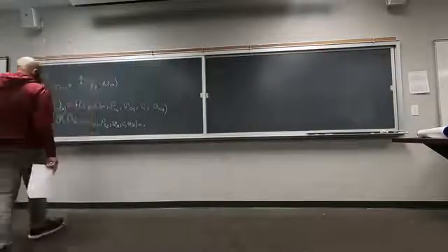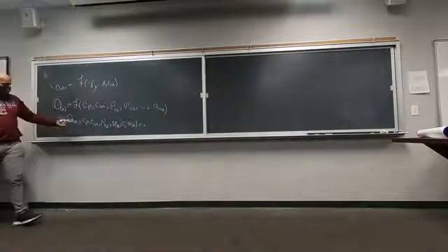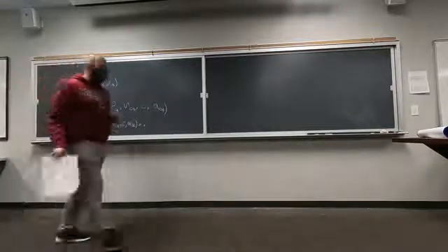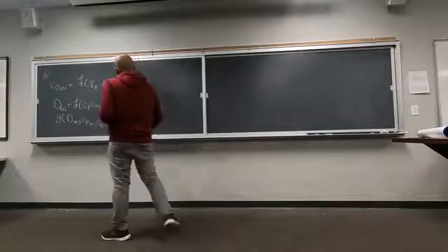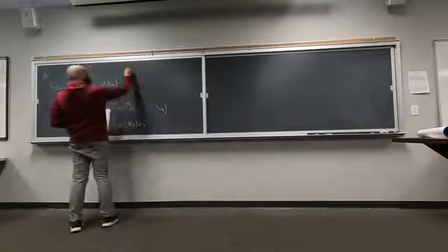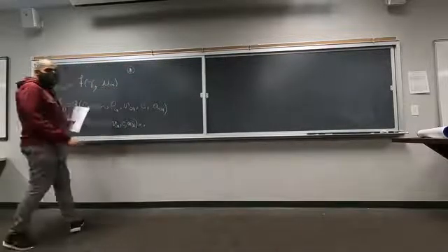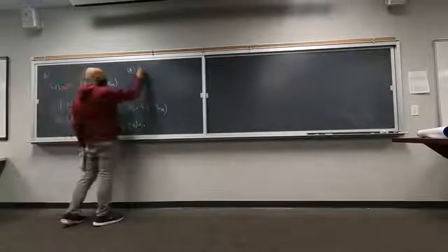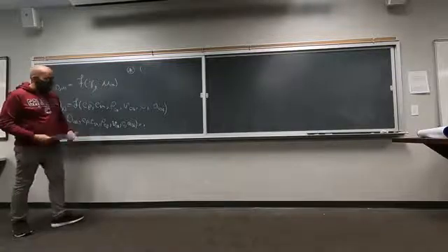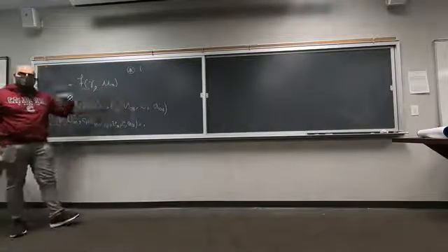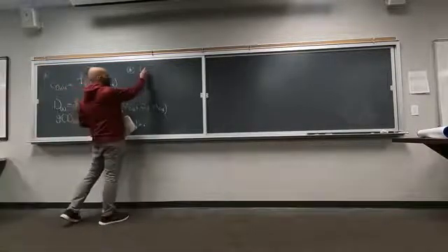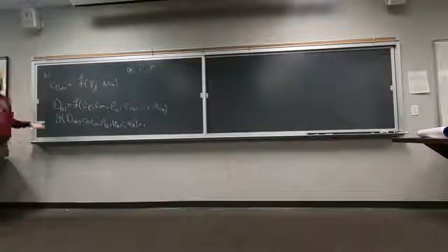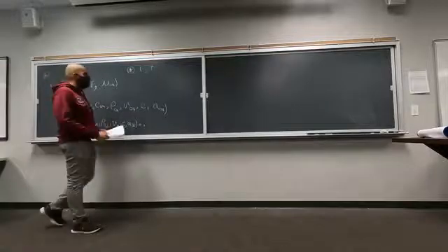Okay, so how many variables do we have? 1, 2, 3, 4, 5, 6, 7. 7 variables, independent and dependent. The other thing we have to count is the number of fundamental parameters. We have length, which is present, for example, in chord length and velocity. We have time, which is present in velocity, for example, again.